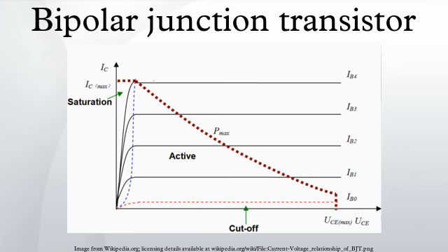Due to low-level injection, the ambipolar transport rate is in effect determined by the excess minority carriers. Detailed models of transistor action, such as the Gummel-Poon model, account for the distribution of this charge explicitly to explain transistor behavior more exactly.